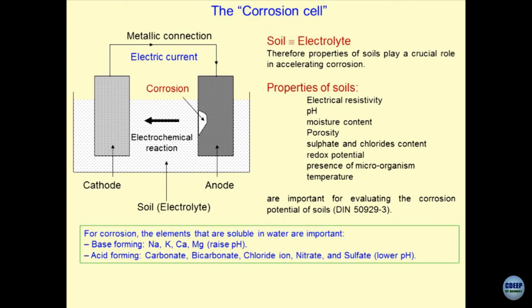Now, what it indicates is that if I take the soil mass which is not dry, alright. So, maybe during rains the soils will become wet, and once the soils become wet, the electrolyte gets developed over there. This could be because of the groundwater also. The moment soil becomes wet, there could be a situation where cathode and anode might get developed. Do not think that they cannot have been inserted into the soil mass. Because of the electrochemical reactions, the chances are that certain portion of the soil might act as anode and certain portion might act as a cathode. That could also be because of the bacterial activity.